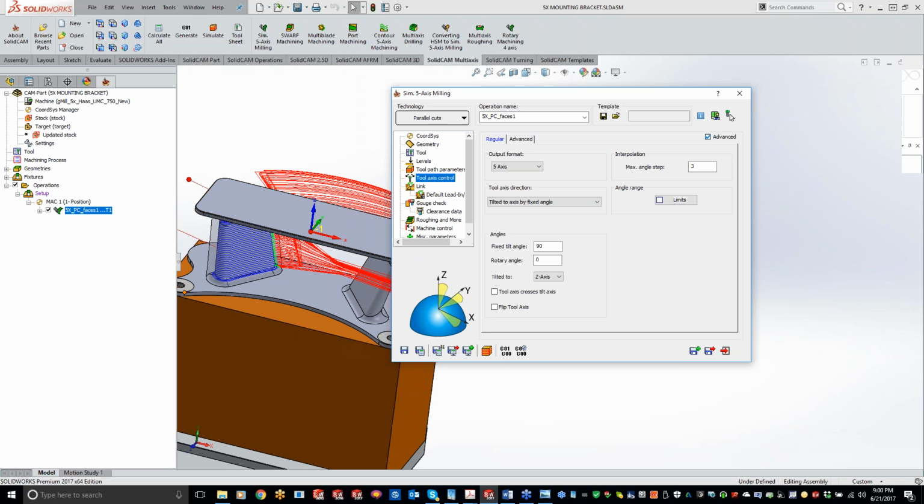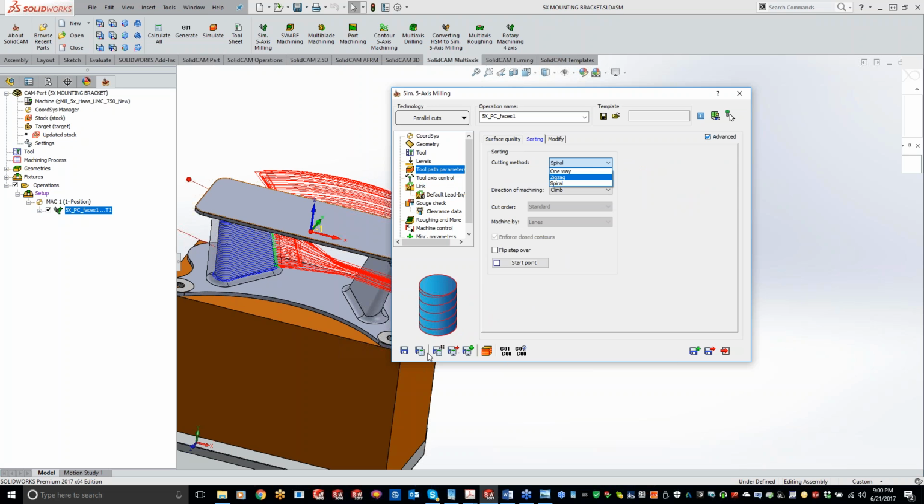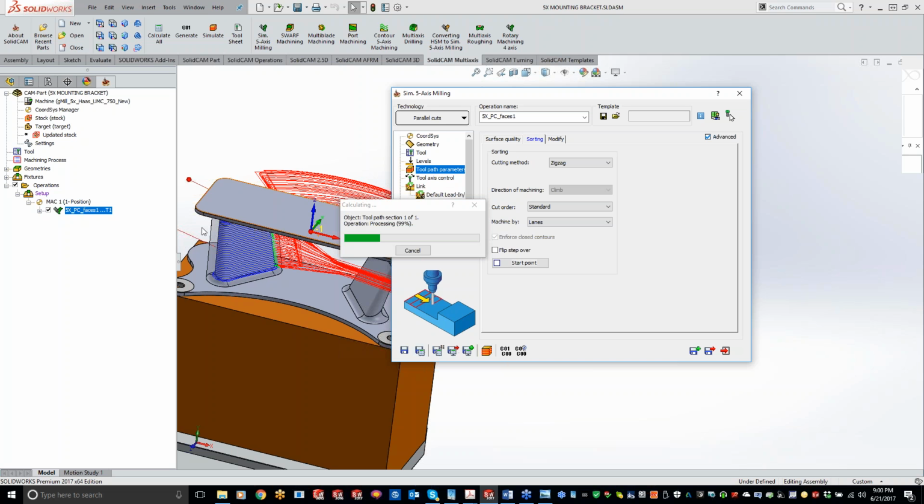I'm sorry. No problem. And James, Zigzag to reduce pickups. Yeah, that actually might reduce some pickups. So let's just try it real quick here. Let's go toolpath and sorting. Let's do Zigzag and see if we reduce some of those. I'm just trying to think, it may not, because it's trying to go around the one circle, doing an entire cut all the way around the surface. But let's just take a peek here. Yeah, I'm thinking we're still kind of along the same lines here.